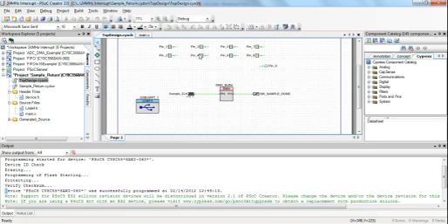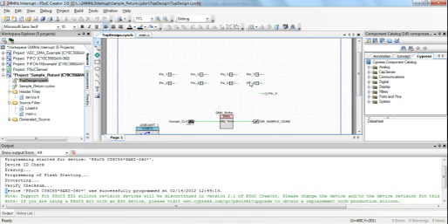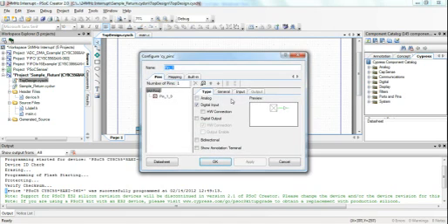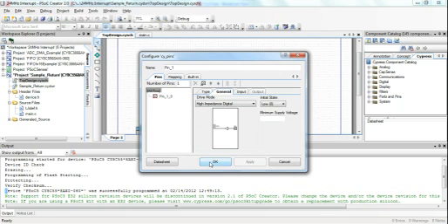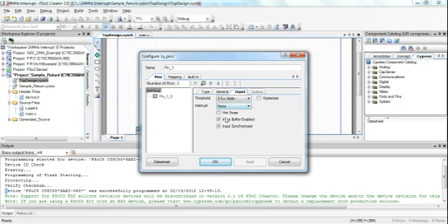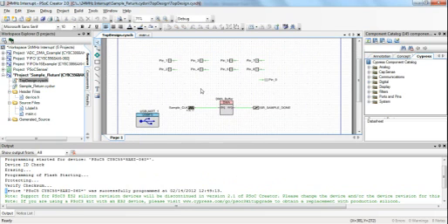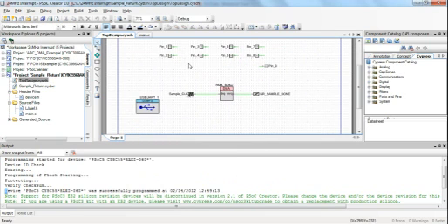So, if you look at the top design of the PSoC5, it has these input-output pins right here, which are just set up as high-impedance digital pins with a threshold of half the input-output voltage, which is 5 volts. So, the threshold is 2.5 volts.